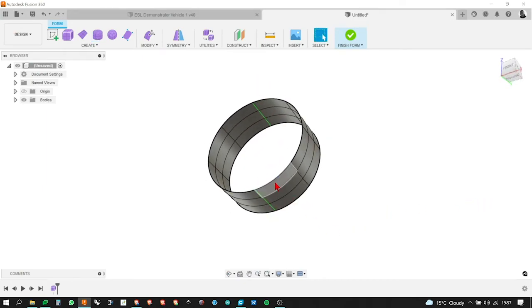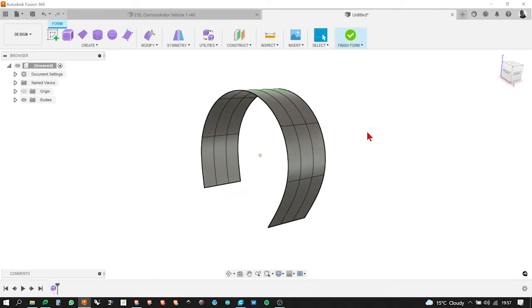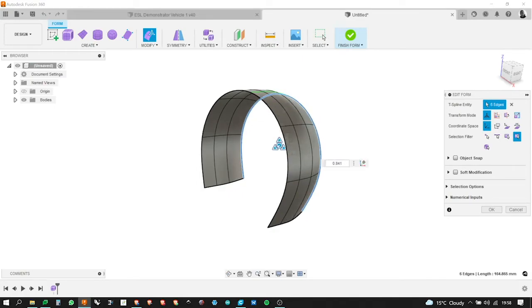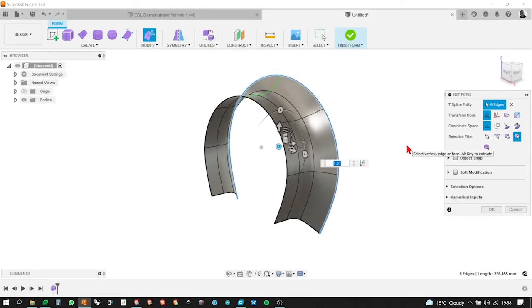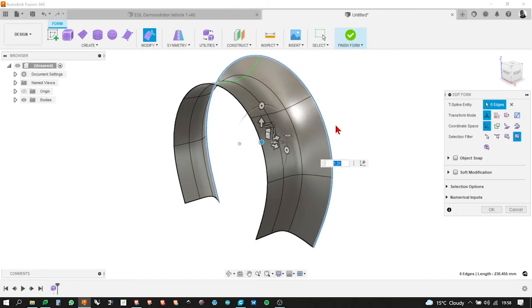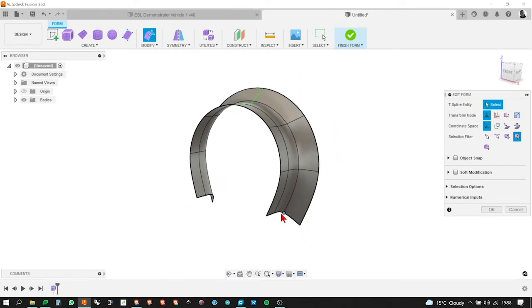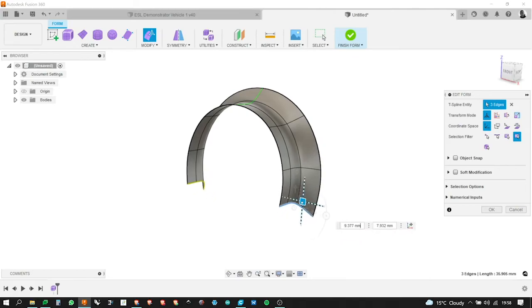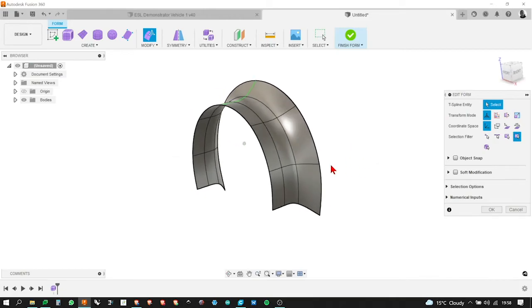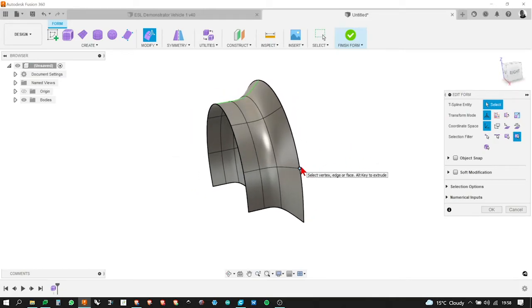But one nice thing we can do in Fusion is delete faces just by selecting and deleting them. And hey presto, we've already got something that looks a bit wheel arch-like. And now if I modify this, very quickly, I realized that I could, I mean, there's a lot more to it than that, but you can get to that shape quite quickly. You can start getting it however you want it to be. I found that's a really quick and simple way of getting that shape, and then I could offer it up to the side of that surface of the car.